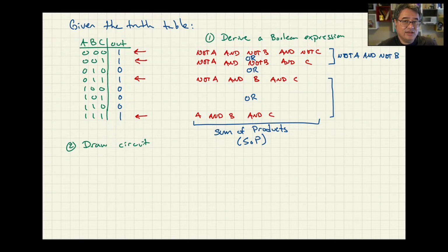What is true about both of them is that both B and C are 1s. And those are the only two rows where that's the case. So now we can just connect those two together with ORs, and we've got a simpler expression. Instead of having 4 terms in it, each one of those AND expressions is called a term, it's only got 2.